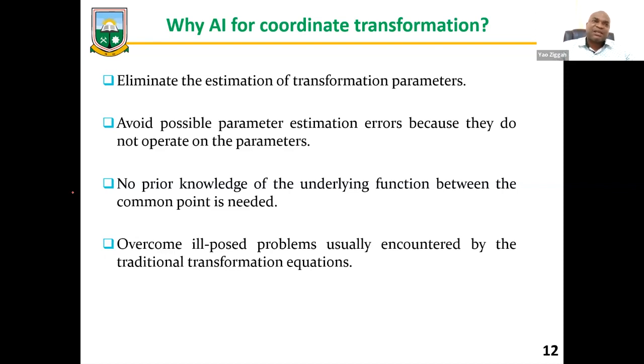When you look at the classical approach, first of all, there is a mathematical formula that has been established that maps reference system 1 and reference system 2 together. And in the course of determining parameters, if your geodetic network is highly distorted, it contributes to the parameter estimation process and the errors incurred after the parameters have been determined. Now, the AI avoids these processes.